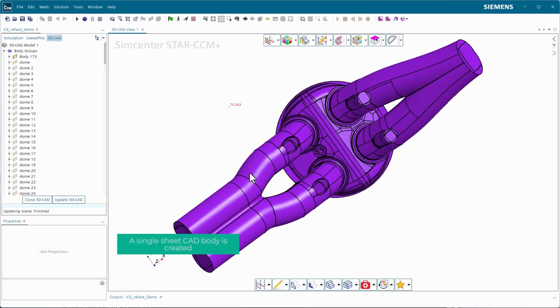Another example that I can give as well is the evaluation of differences that occur between the geometry used in the CFD simulation and the actual geometry manufactured. As you know, Rodolfo, the manufacturing process typically introduces some defects, and in certain instances, those defects can have an adverse effect on the performance of the part. Utilizing the new Mesh to CAD feature, the user is able to scan the manufactured part independently and then use that scanned data to create a CAD representation, which can be further analyzed to ensure that the performance is what is expected of it.